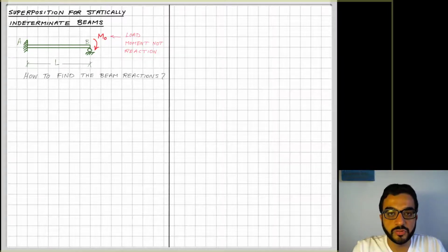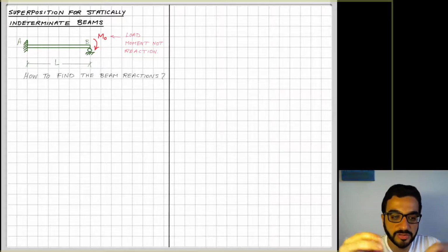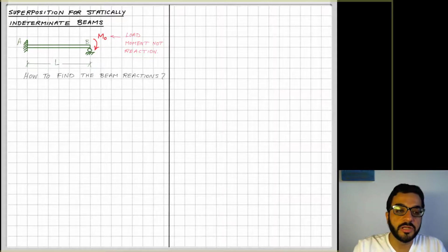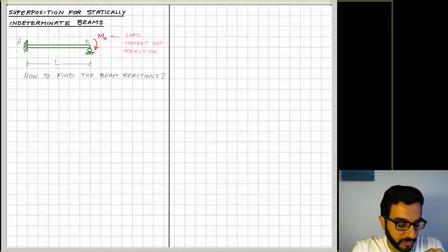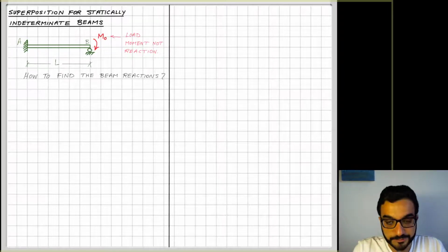So the first thing to be able to design the beam is to figure out the external equilibrium, calculate the reactions on the beam, and then I will be able to calculate the internal forces on the beam, and then the stresses at points and principal stresses and all of that fun stuff. So we are stuck at the first step and we don't know really how to solve. We have 4 unknowns, 3 equations. And then deflections, or strength of materials, will come to save us here.